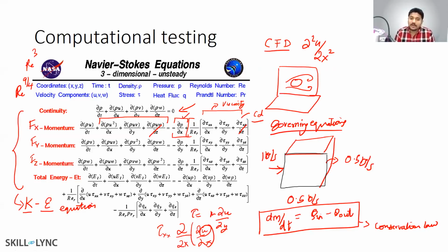So in other words, you cannot capture turbulence by directly solving these equations. So you're trying to approximate it, and that is where the turbulence model comes into play. And we have something called the law of the wall, which helps a turbulence model so that even with a larger cell, you can run turbulent flow simulations. This is an important point in CFD. Many students who run CFD simulations think that when you use a turbulence model, you're accurately capturing turbulence.